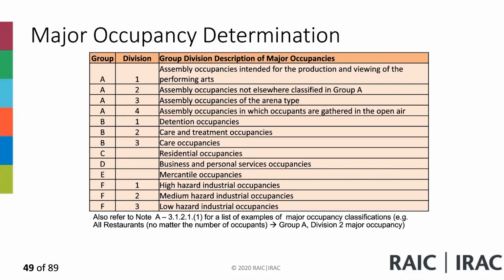If you have an F2, it's the most conservative approach, and the sales room could be a subsidiary to it. Or, depending on how big the sales room is, you want to do an occupancy separation, and you have less requirement for your sales room than your Group F2. So that's how you want to take a look at it. Thank you. Okay.